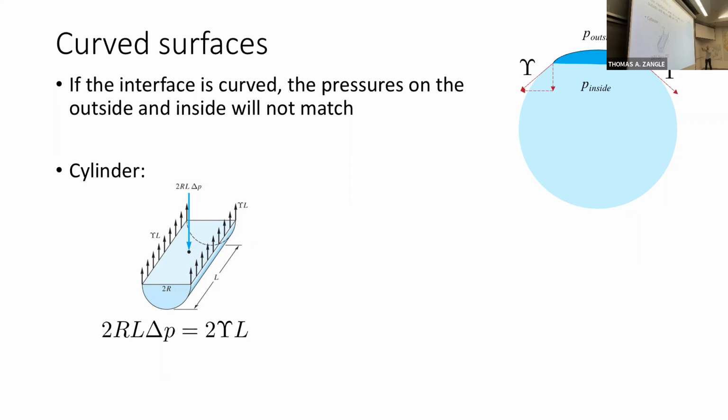But if we consider the X components, they actually would all cancel. If you imagine this like skin, taut skin of the balloon of this water droplet, caused by surface tension, the X component going all the way around is always of the same magnitude and pointed in all different directions, and so that cancels out. And the X component of all these pressures, exerting inwards as we move all the way around the whole surface, they actually cancel out as well. So the only case where we are really learning something is in the Y direction here.